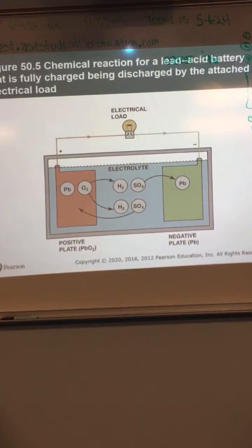How can you make a battery blow up? Why would you want to do that? Okay, since batteries do emit kind of an explosive gas, a battery can explode if it happens to be gassing and you create an electrical spark by hooking a jumper cable up to it, charge or something like that. I've had it happen to me. I had a battery explode on me one time.